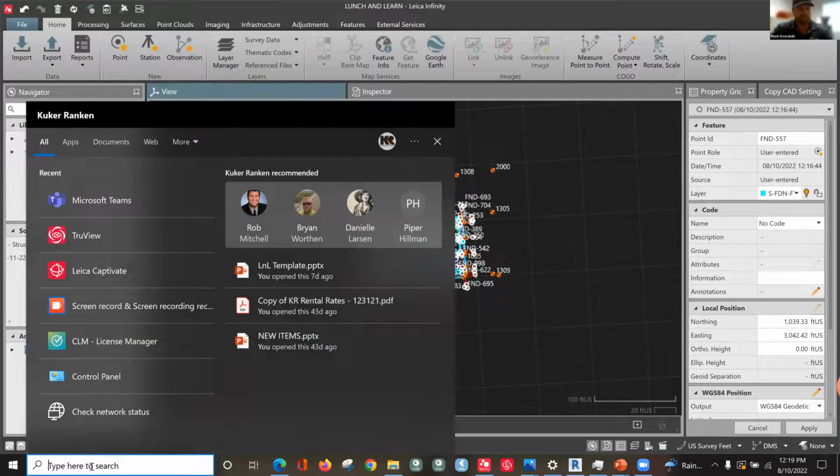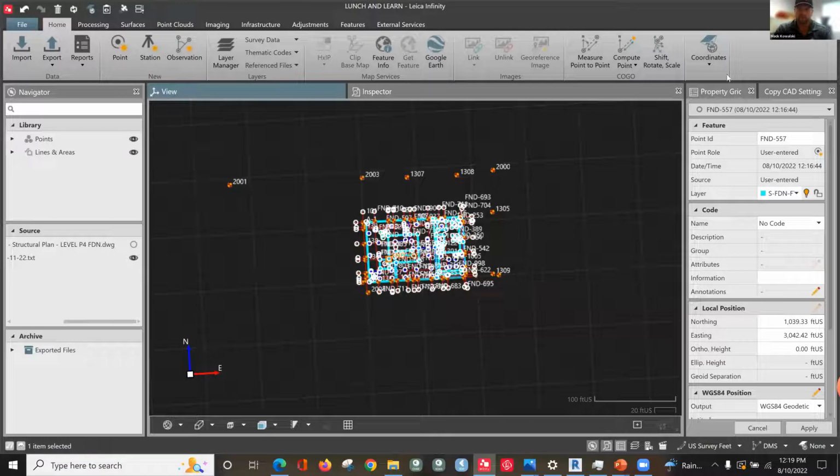Now, we're not actually going to go into Captivate on this one. The simulator I have is not performing well on my computer, and it would be futile. I will, however, talk you through it. If you were to import an ASCII and then a DXF, you run the chance of importing it XY instead of YX, or importing it in meters instead of feet.